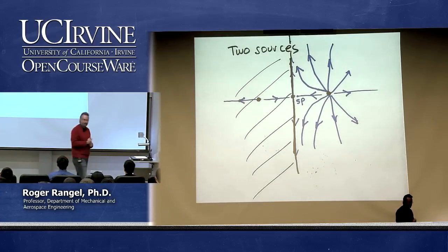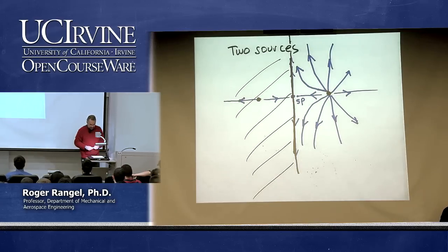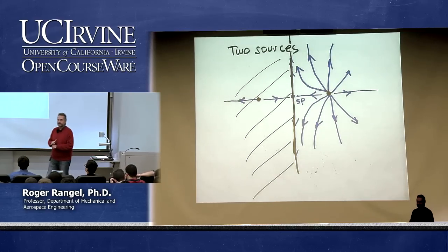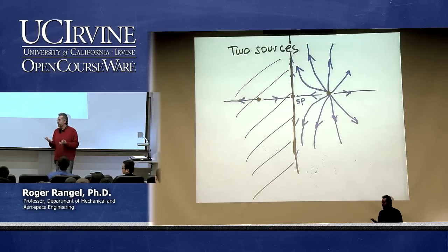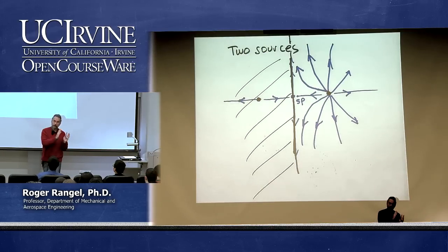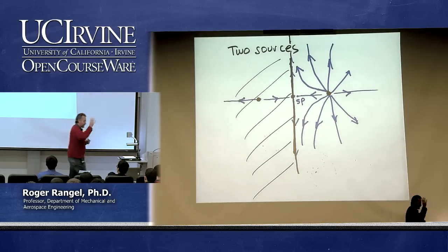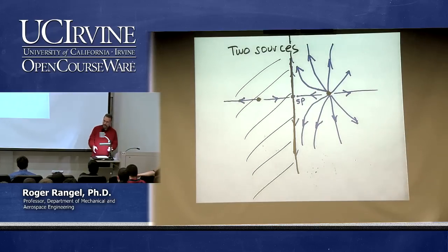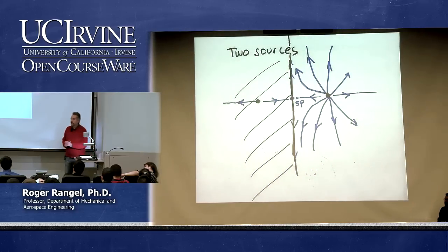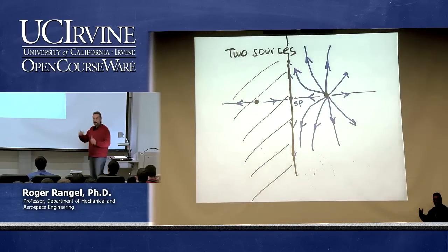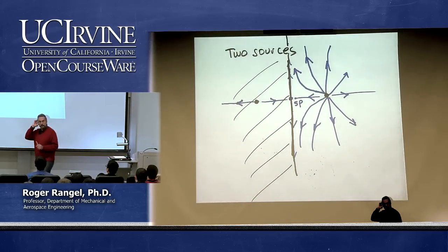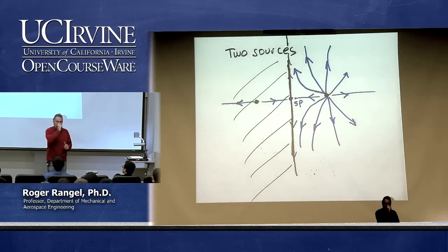Lower. Yes, why? It's moving faster. The fluid is moving. And remember, the one thing that we cannot do with these potential flows is satisfy no slip. So the flow has to slip past that wall. We can fix that later by learning other things, but not here. So the flow is just slipping by, and therefore, since now it has some velocity higher up, from Bernoulli's equation, the pressure will have to go down, right? So the pressure will drop.